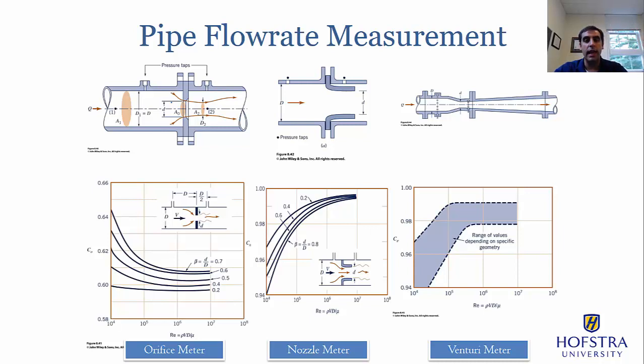So in the lab, we're going to know what the flow rate is by traversing that pitot-static probe at the exit plane of the pipe, which I mentioned earlier. And since we then know what the flow rate is, we can back calculate what the discharge coefficient is if we simply measure the pressure before and after the orifice, where the orifice is simply like a flat plate stuck in the pipe with a hole drilled out the middle.